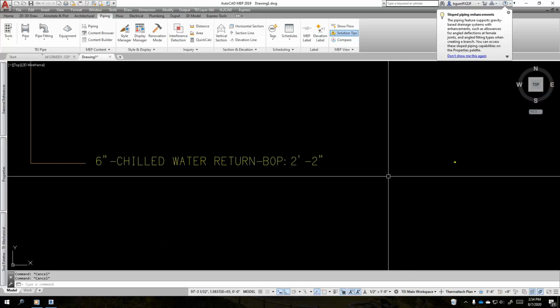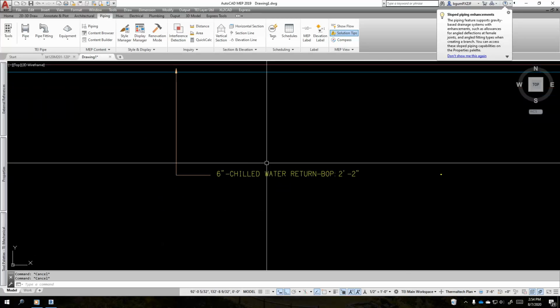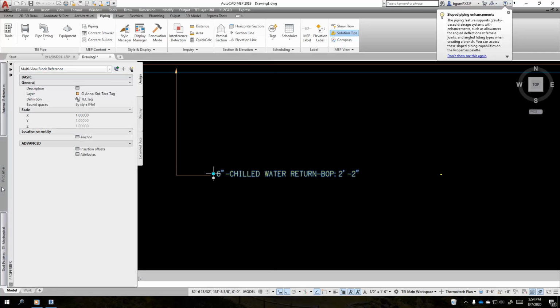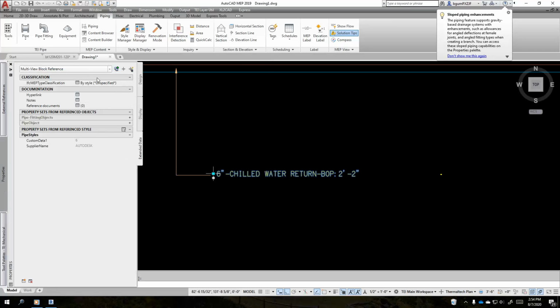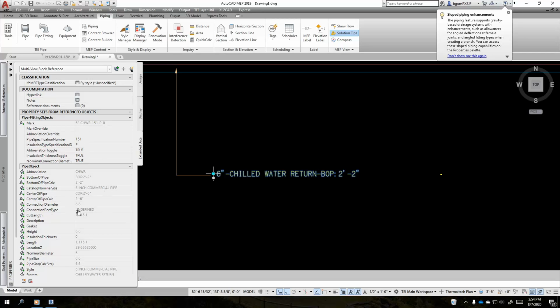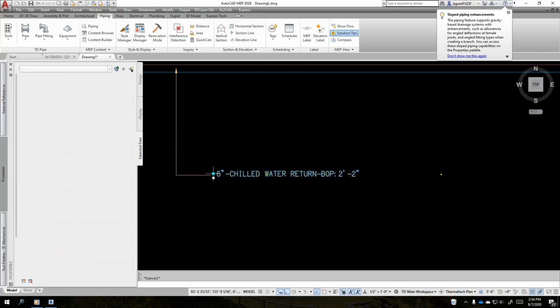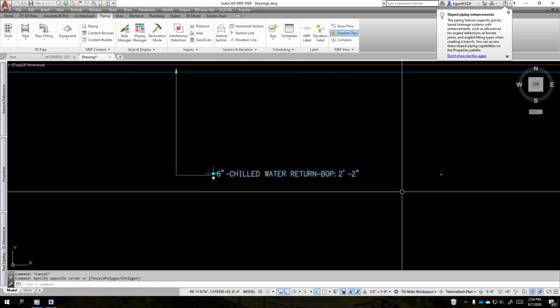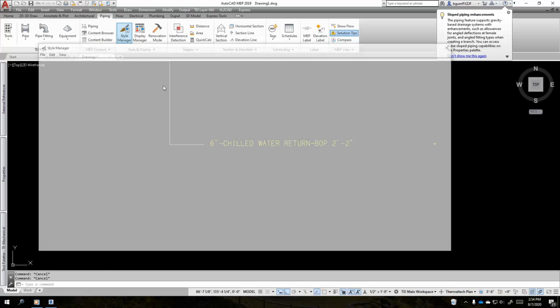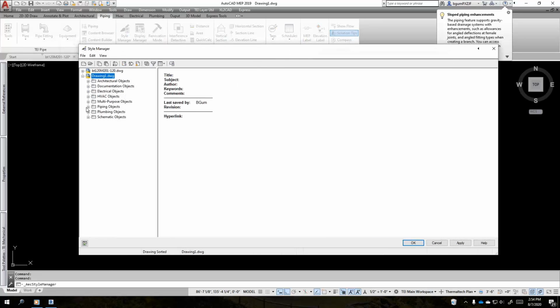And lastly, we're just checking a few last things. So what happens if you need to edit this for whatever reason? So this is actually a multi-view part. And so you can change this stuff here, and you go to extended data here. And if we expand some of this stuff, you can see all the extended data associated with that pipe. But there's actually a block associated with this. And so the name of that block, there's 2 ways to find it out. Either you remember what the block name is, which should possibly be the same as your tag definition.